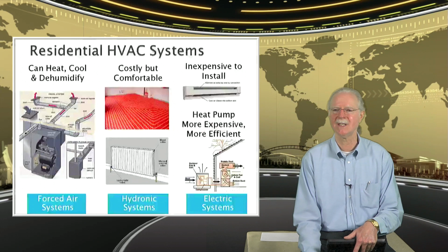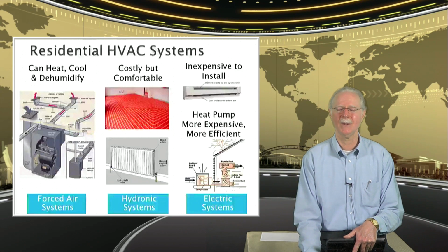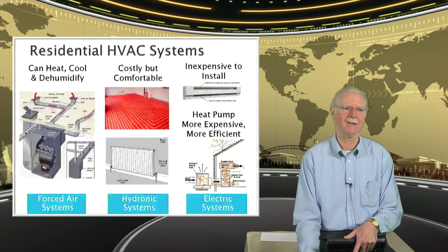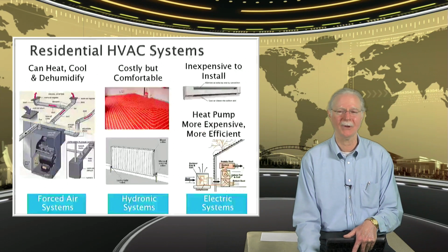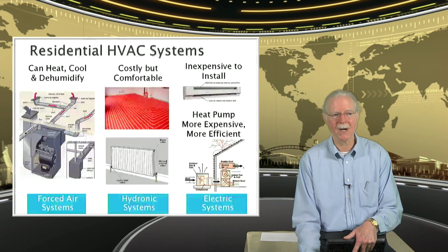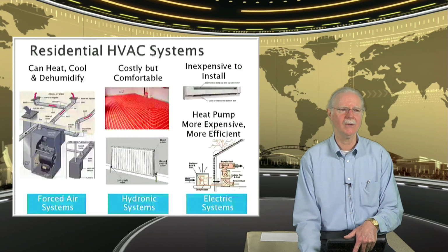And we lose efficiency. The amount of efficiency that we lose is amazing. We're dealing with end-use efficiency of the burning of that flame of something between 20 and 40%. So we could have lost anywhere between 60 and 80% of the energy that was available in what we burned to create the energy. That automatically makes this electric resistance heat an inefficient and expensive way to heat. So if we have no other option, if we must use electricity, how can we do something more efficiently?